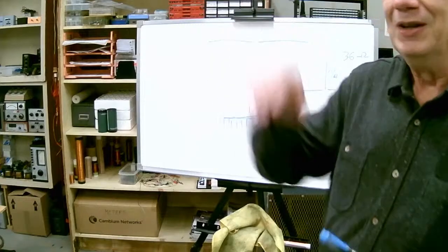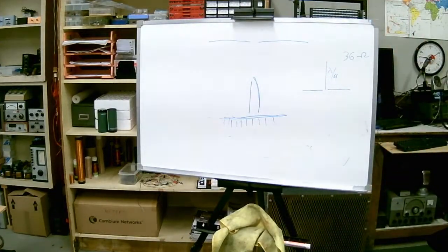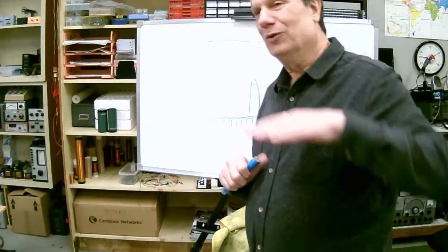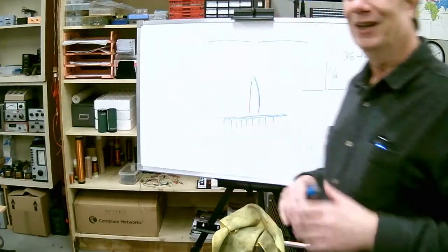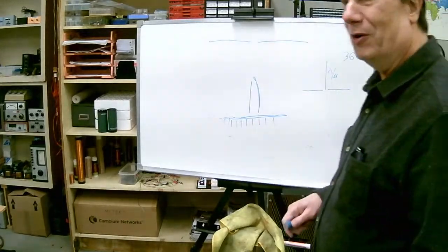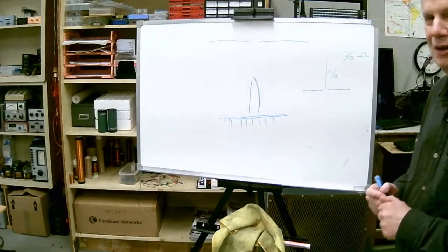If you've done any flying where they use ADF receivers or ADF transceivers for direction finding, and you fly directly over the AM broadcast tower, the signal is gone. There's a kind of cone of silence overhead. But the whole point of AM broadcasting is transmitting very strong signals at ground level.